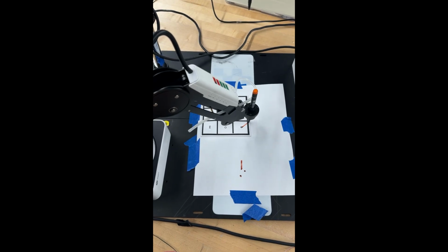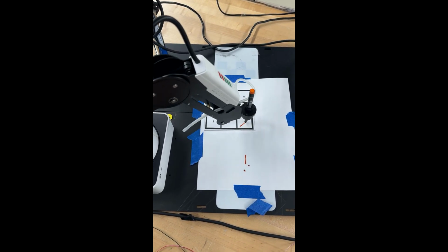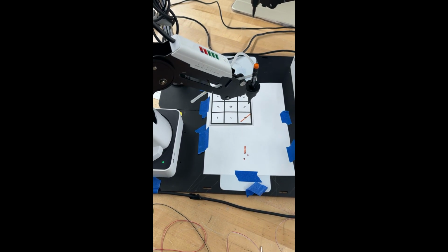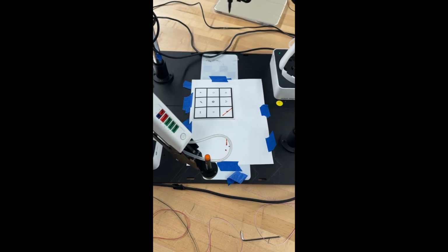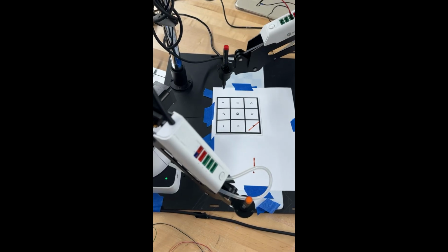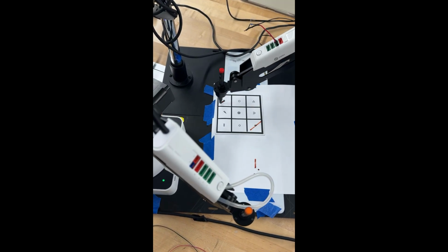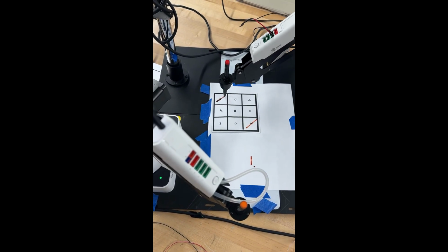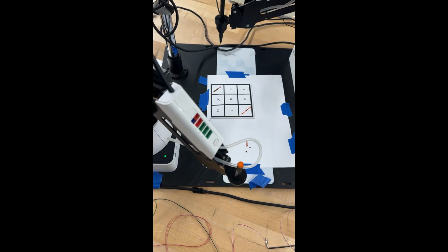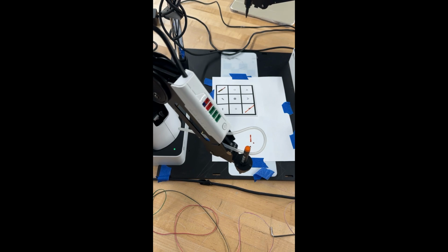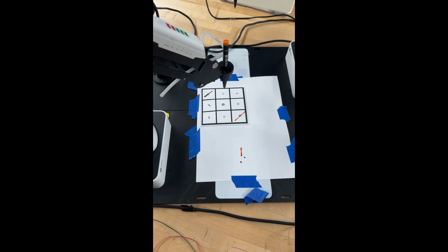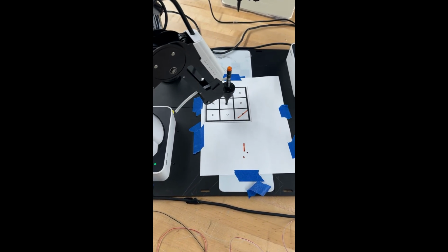Lastly, the first robot moves out of the way and sends a signal to the second robot. The second robot uses a branch after the receiving code, which causes the robot to wait for a signal and proceed only when prompted to by the first robot. Thereafter, the second robot carries out the same procedure to choose a new square on the board. During this, the first robot waits for its turn using a wait time block.